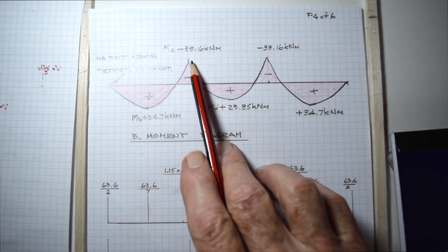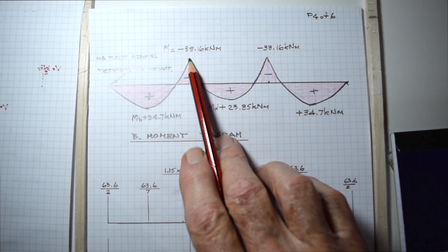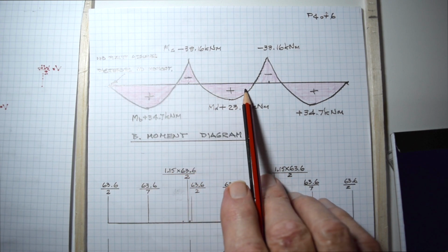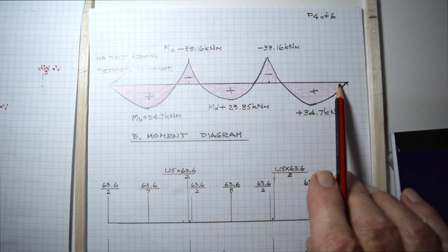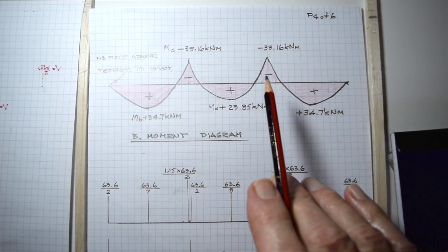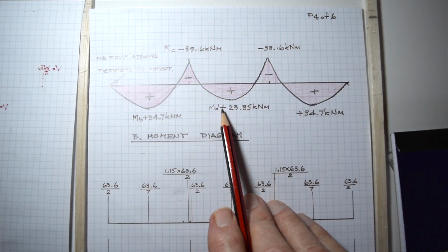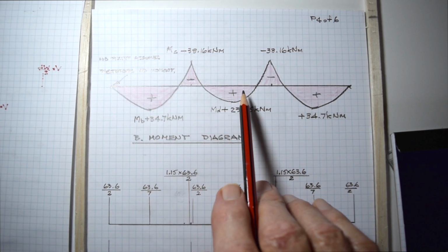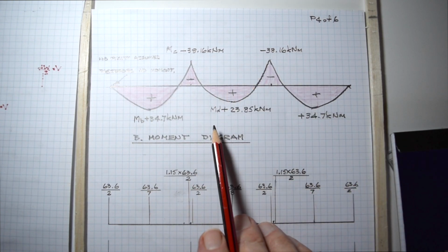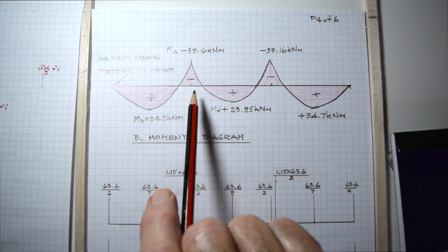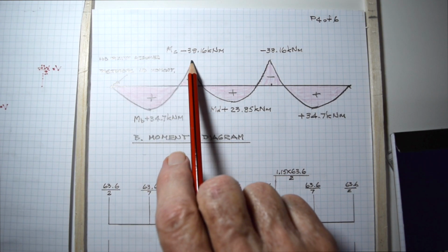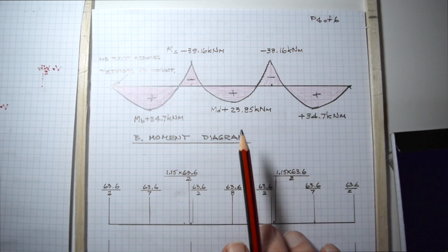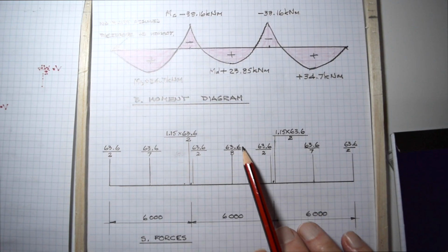Your maximum negative moment at the first interior support, where the beam follows, in deflection, the bending moment diagram like that. That's why we draw it upside down. It makes mathematicians' hair stand on end because we are putting a positive below the baseline, but it suits structural engineers around the world. There your maximum negative moments are. By symmetry, same on this side. So that's your bending moment diagram.